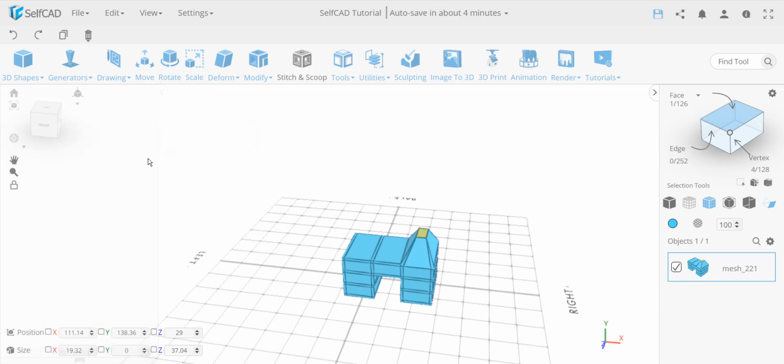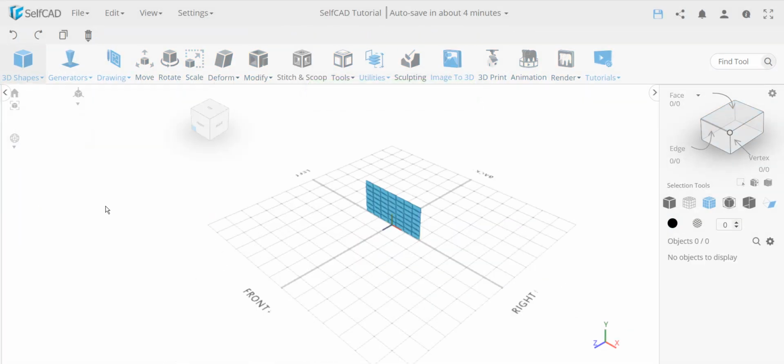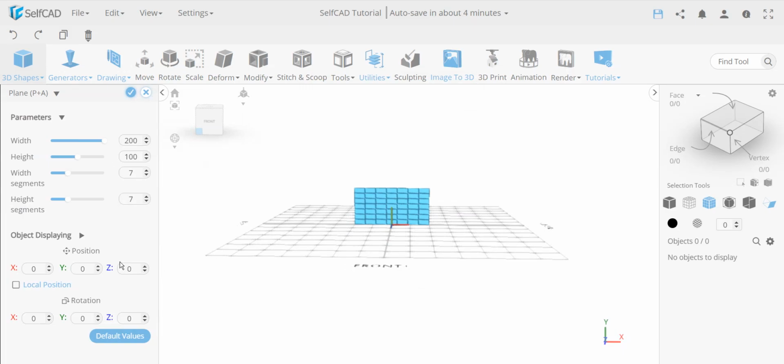In order to illustrate that, I'm going to use a basic shape to illustrate another example first, the transformation tools. I guess I can use again the plane that I've created. I'm going to use just segments like this. The height segments I'll leave, and the width segments, maybe I'll make this 10 segments, and the other I'll leave at just 1.